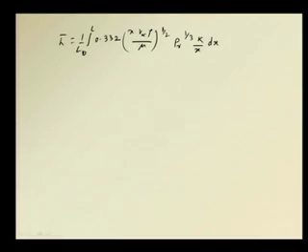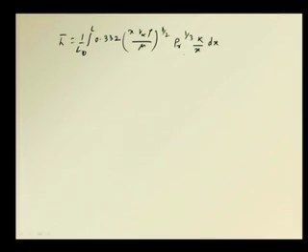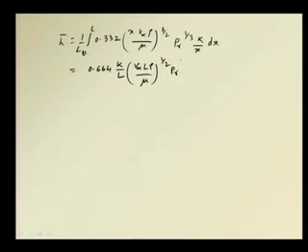So, k by x, this is becoming the expression, and then we have to go for integrating these. All other parameters are constant, except one related to x to the power minus half. Other things are constant. So, from this we can find out that this is equal to 0.664 k by L, (V infinity L rho by mu) whole to the power half and Prandtl to the power 1/3.